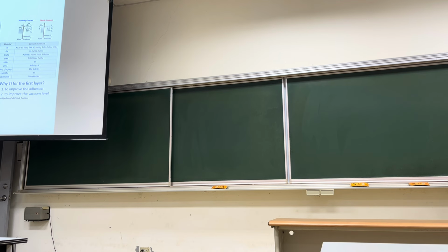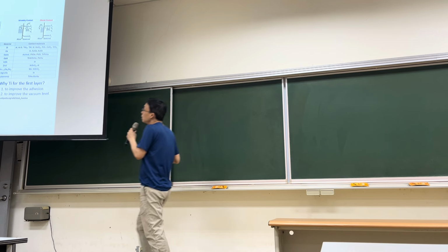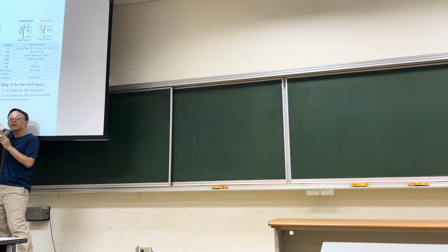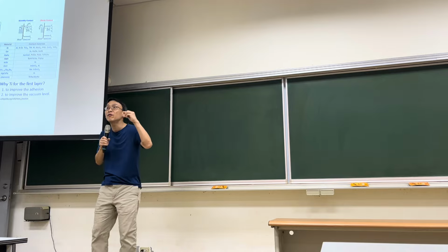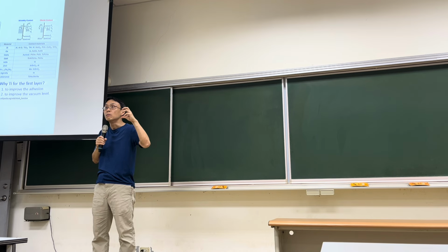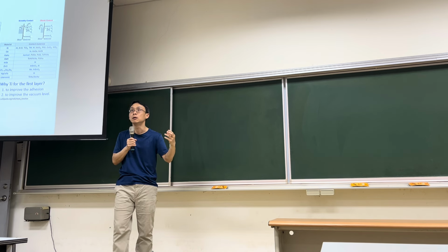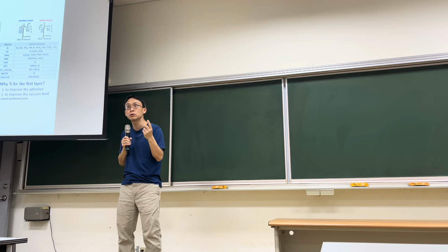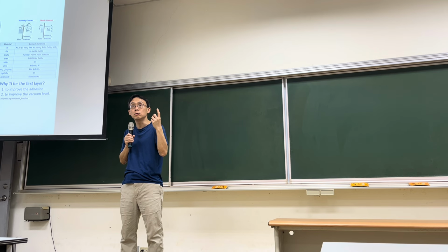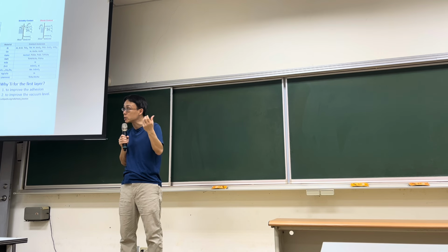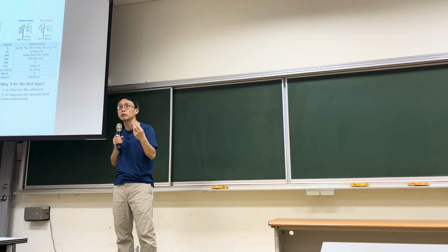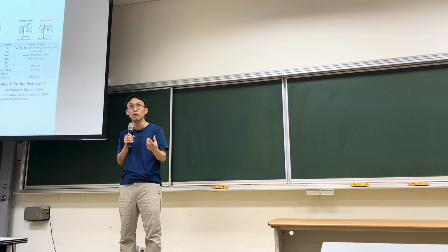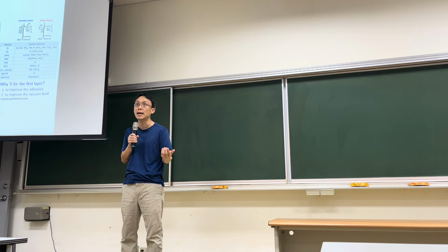Alright, so this is the work function of many different metals. It's like a band gap of a semiconductor, which is a fixed value. Before you choose the metal for the contact, the first thing is to make sure you are achieving the ohmic contact or Schottky contact, because that's the result of the work function. If you choose the wrong work function, you will have the wrong contact, right?